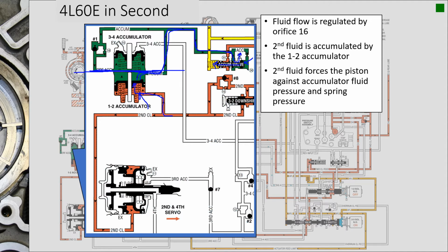And that's the job of the accumulator. If you remember, the idea of the accumulator fluid was to create a variable back pressure on this accumulator piston. So when fluid pressure came in here, in most cases it would compress the spring, but in this case it doesn't. But in addition to just stroking this piston, it'd have to squeeze the fluid out.